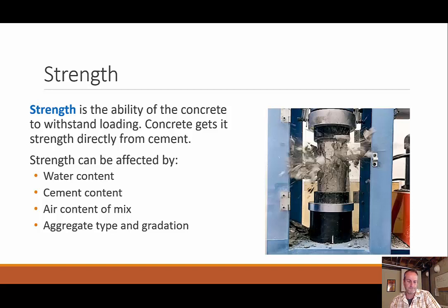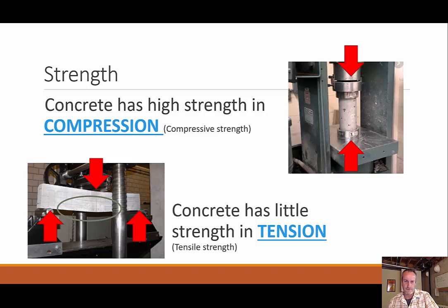So the key factor about concrete is it's really strong in compression, but it's not very strong at all in tension. And so what we can see here on this bottom one is like a beam. If you think of how a beam works, when you're bending a beam or putting a load on here, what happens is the top of this beam is in compression, so it's nice and strong, but concrete is really weak in tension. Well, that's what's going on in the bottom part of our beam.